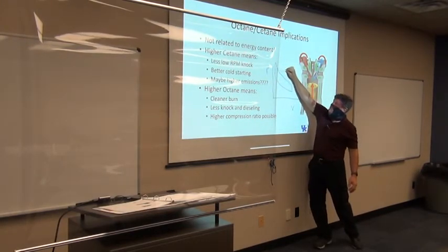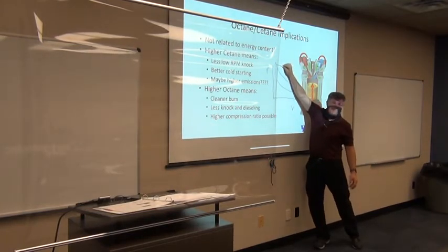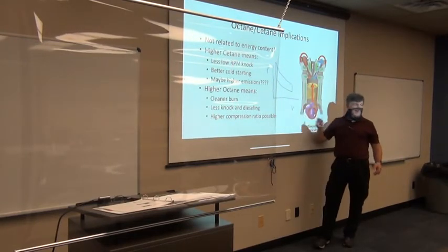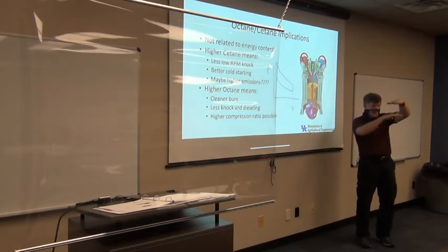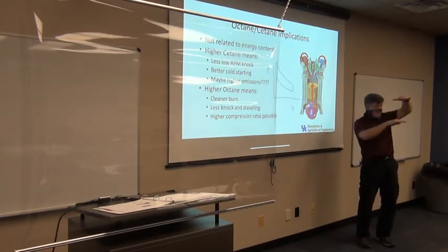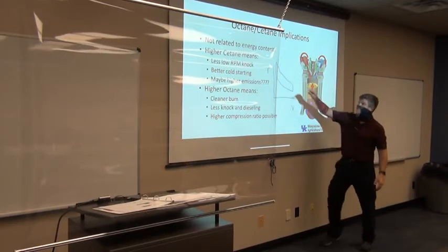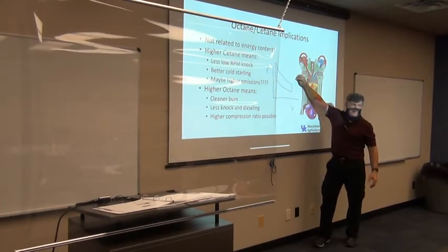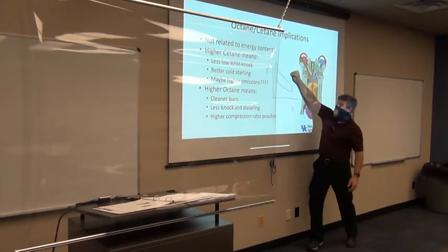And then what's coming down here? What is this, the top part of this curve? Pressure is coming down. Volume is getting bigger. If the volume is getting bigger, that means the piston is coming down. The volume above that piston is getting larger. So what stroke is this then? Power stroke. Yeah, that's your power stroke. That's the power coming down.